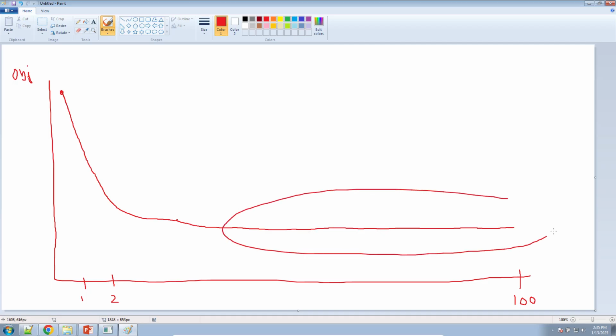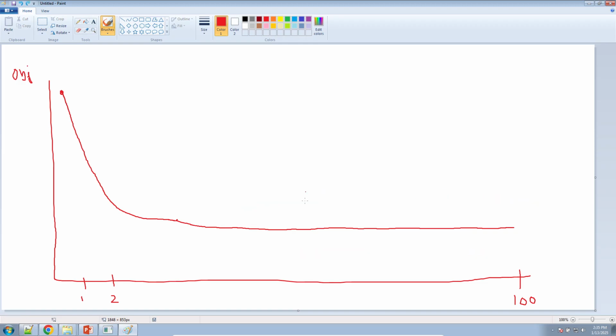So all of this is yielding no improvement. So what you can do is the following. You can say, you know what? Terminate here. At 50 design cycles, stop the topology optimization, because I know you are not going to make any more progress. Most of the improvement has been made within the first 50 design cycles.